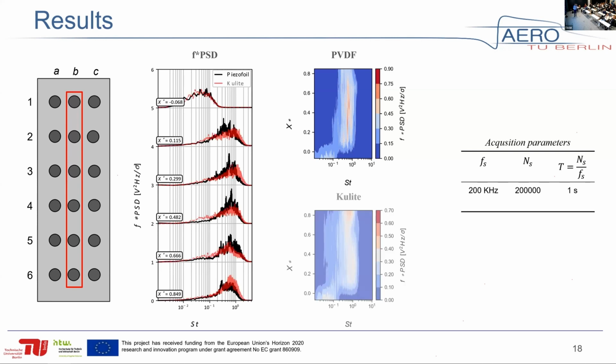And if we compare them with the Kulite measurements taken in the same flow, the Kulites being state-of-the-art pressure transducers used for pressure fluctuation measurements, we can see that they are matching quite well. We cannot yet use it for actual pressure values because of the temperature issues that we are trying to solve. So these are just voltages, normalized voltages. But I think already the dynamic behavior of the sensor is matching quite well with the Kulite.